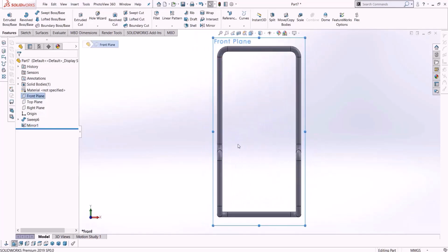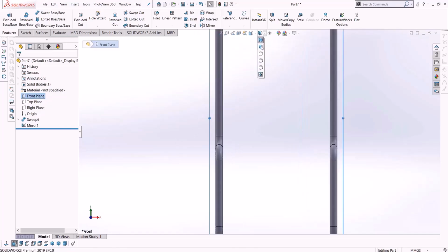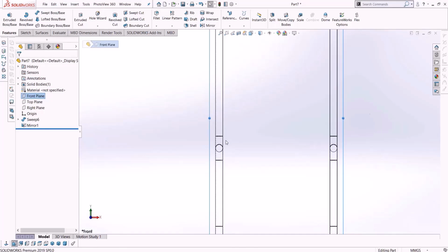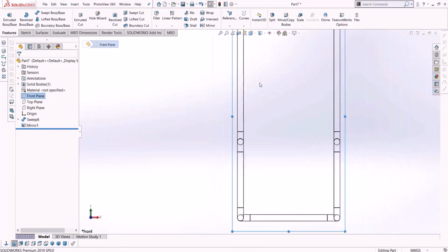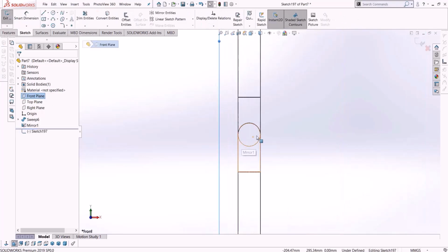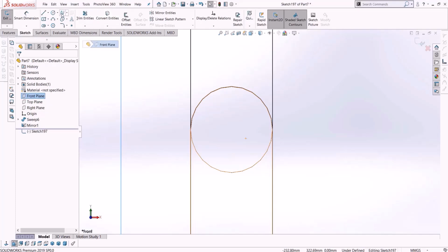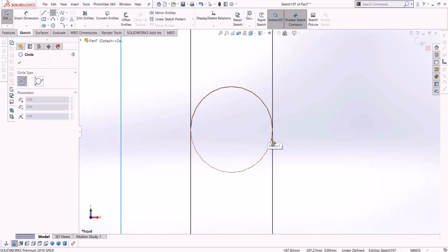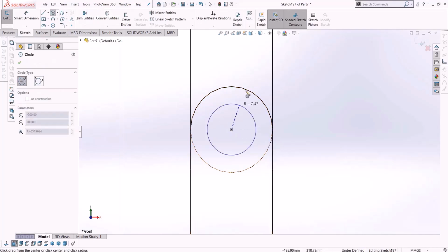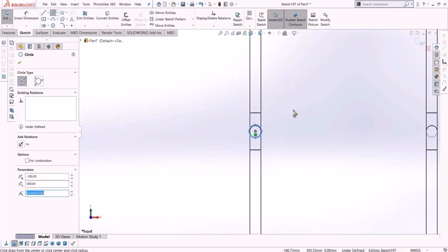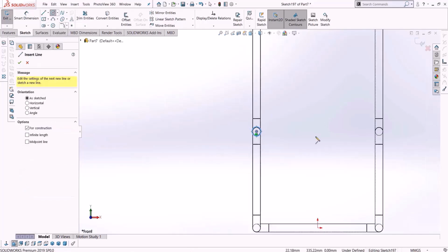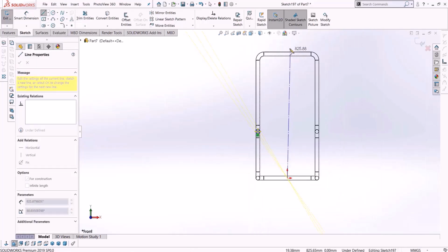But now, what should we do about the upholstery and such? Let's make it look cooler and more aesthetically pleasing. We choose a front panel to create a covering for the chair's seating area, which is an essential part of the overall design. I select the front panel and sketch it meticulously. Here, I draw a circle relative to the profile we have and create a center line in the middle, ensuring precision and accuracy.